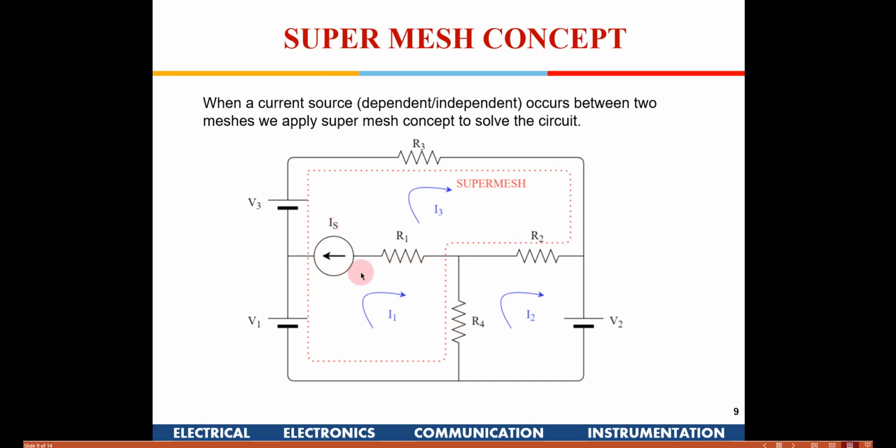So you have something which is not going to be defined easily, so it will become difficult for us to solve these kind of problems where you have a current source in between. It could be a dependent current source or it could be an independent current source, whatever it is. Any current source which is there is likely to not give us a straightforward solution. So in that case, we can use a super mesh. Okay, a super mesh is something like that. We are trying to take a mesh in which we are bypassing the current source. So that doesn't come into the KVL equation.